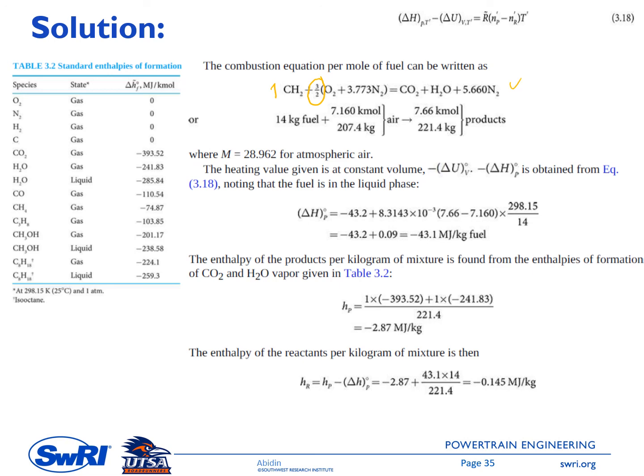And then you can see in here for the mass balance, we have 14 kilogram of fuel requiring 207.4 kilogram of air, and the product we have 221.4 kilogram.